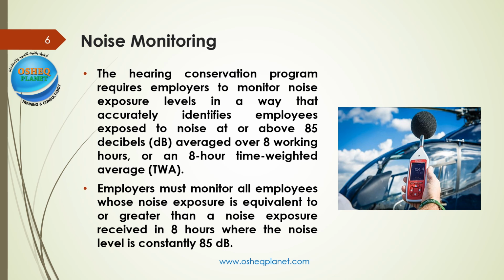One of the principles required by this program is to identify workers who are exposed to an average noise level of 85 decibels or higher during one shift, 8 hours per day, and to monitor them in order to find out early on any change that may occur in the workplace in terms of the noise level to which they are exposed.